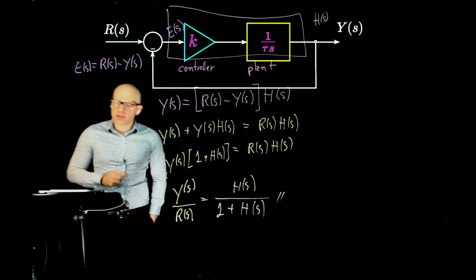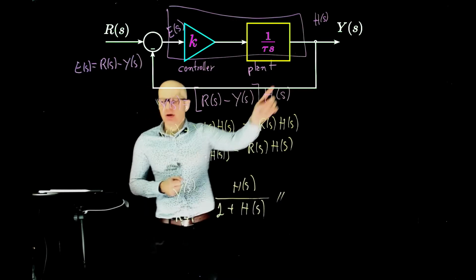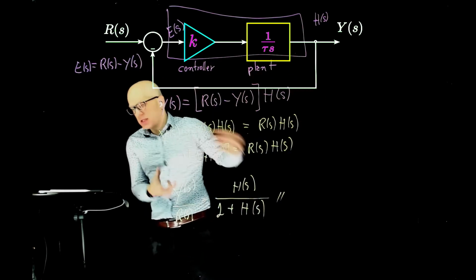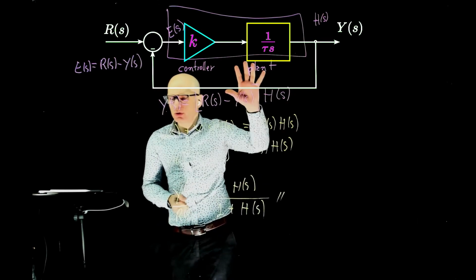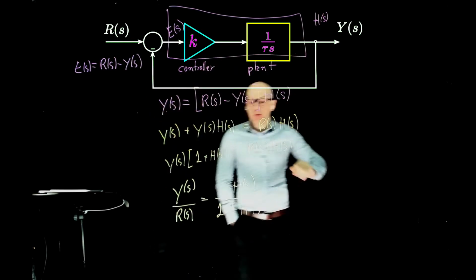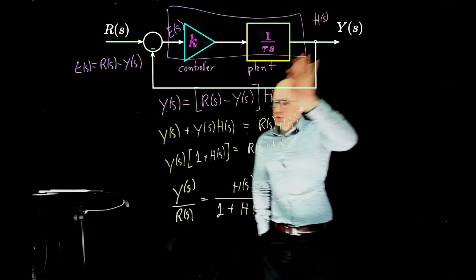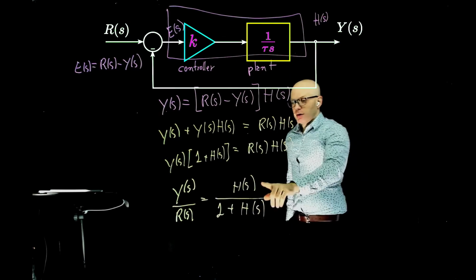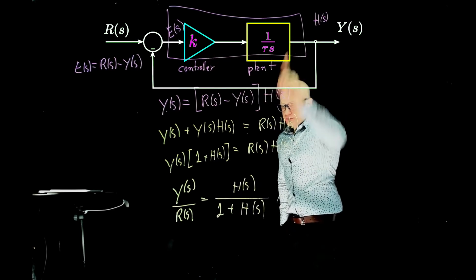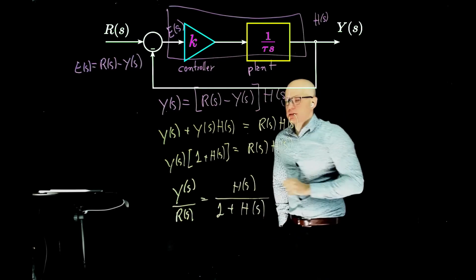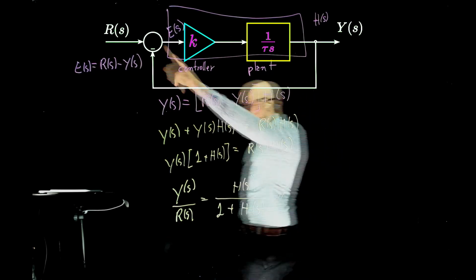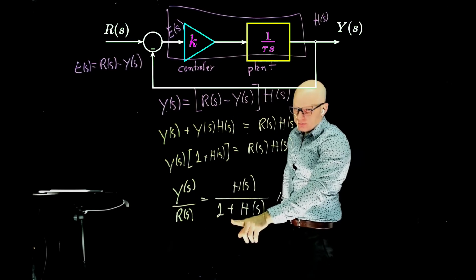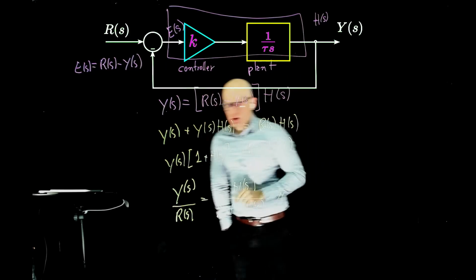It will always follow this format, provided that we have a unit feedback loop here. There's no function in there, but you can expand this equation to include a function. For now, we don't have it. When you close the loop like that, we always end up with a transfer function following this format: the open loop function divided by 1 plus the open loop function. If this signal here is positive, then this signal here will become negative. Okay? But when it's negative, it's positive like that.